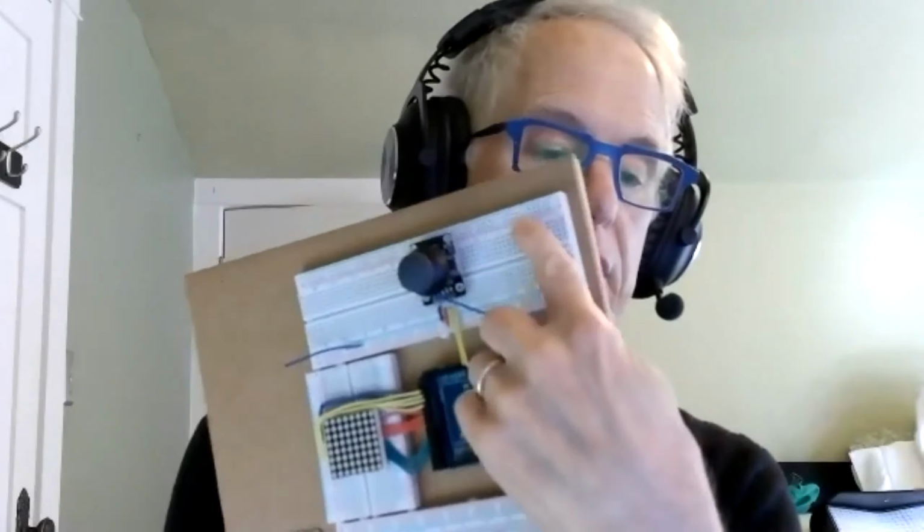These wires are often stranded or the wrong diameter. The thing about these plug-in solderless breadboard strips is they're really good, but you really need to use the right wire. If your wire is too big and you jam it in, or you jam in a big resistor lead, you can break open the contacts, and then from then on you get unreliable contact.